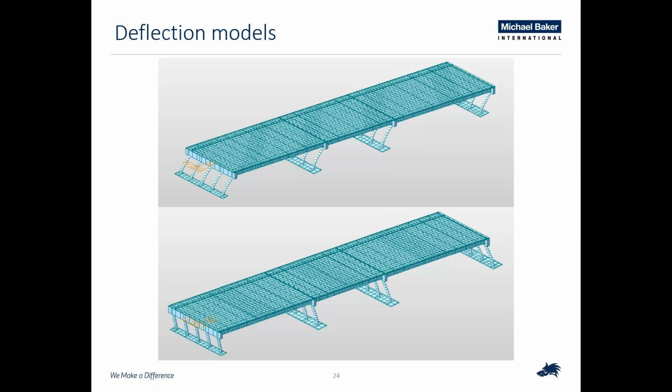And so we had to do some balancing of the stiffness, had to add some piles to some of the abutments in order to avoid that sort of thing. And so once we were able to do that, then we were able to get the deflections for the model to be lower than the design requirements.